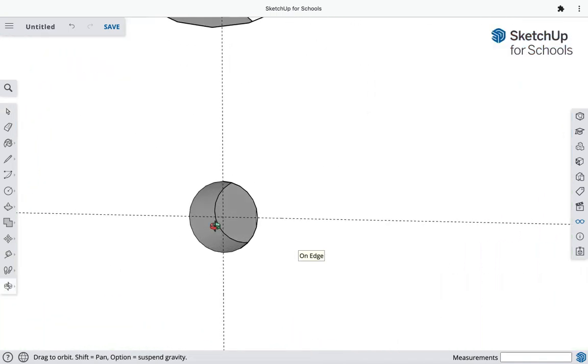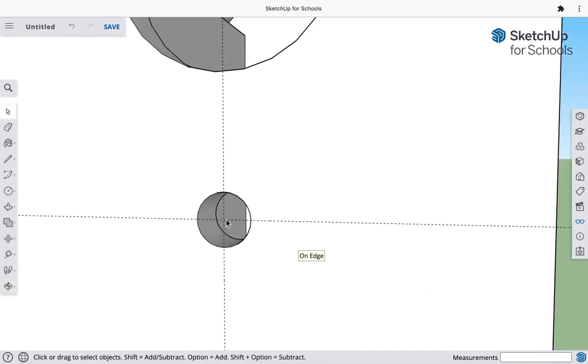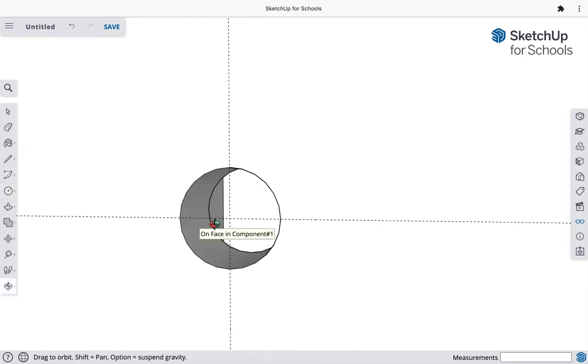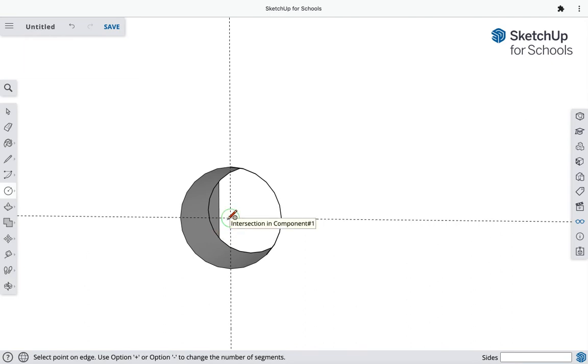And so think about it. The dowel is a different piece of wood, right? This circular piece of wood that the birds are going to sit on. It's a different piece of wood. But we will need our circle tool. So pull up your circle tool and go back to this intersection. You see mine wants to be red. I don't want it to be red. I want it to be green. So if I needed to lock it into green, I could press the left arrow key. And now I'm going to make it this exact radius, 1/4 of an inch from the center to there.